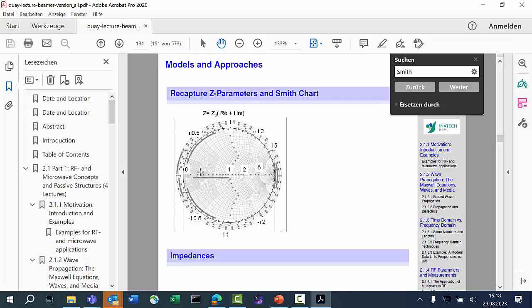So it's a matter of power. And then you select to look at your system as a low impedance system, and you just tell your program, we are now looking at a 1 ohm environment, and then you get these nice graphical representations. It's simply like enlarging. The only thing you must not mix is looking at one component in one reference impedance and the other components in another. This will give chaos.